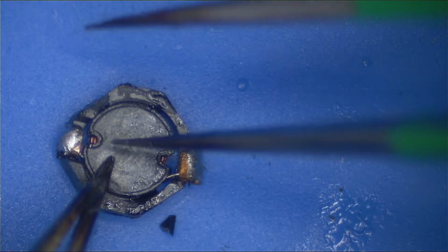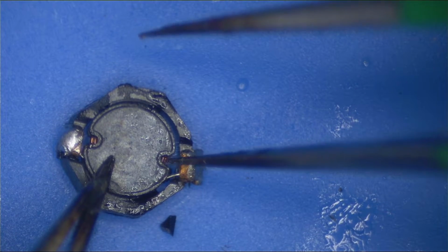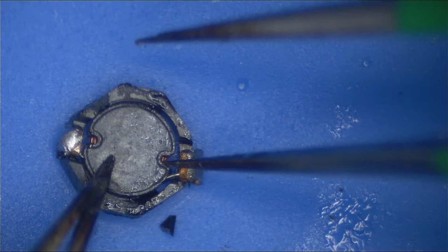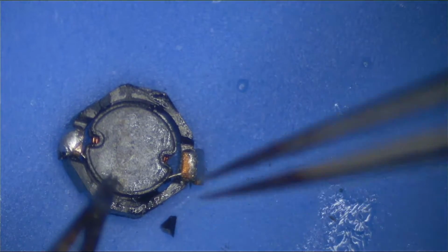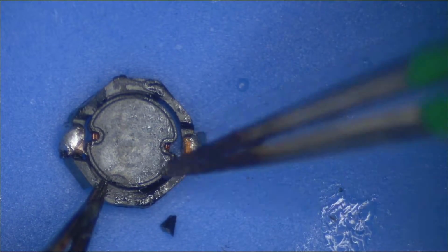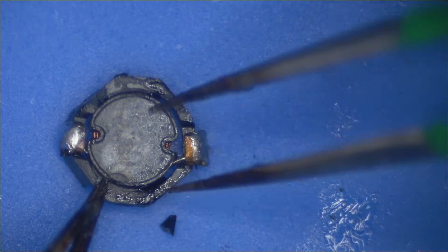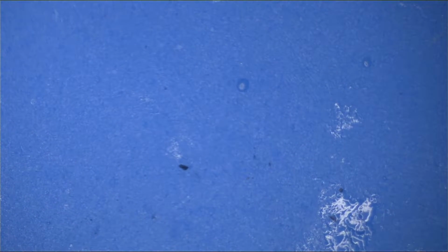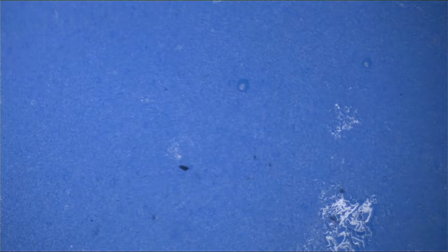On the iPhone 6, these will somehow short together on the inside. The coating will come off because it's a short circuit and there's so much current all of a sudden flowing through that it'll burn through the coating and short some of the windings together, and result in a coil that is not of the right specs or has a partial short. It's really hard to measure. You need a really accurate milliohmmeter to be able to measure that. So this is something that you can't really tell without replacing the coil, practically speaking. And so that's what we're going to do here.